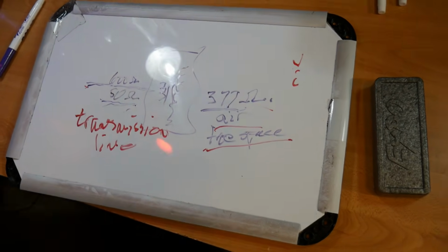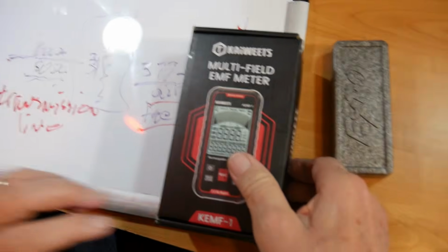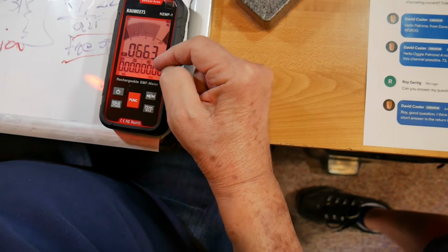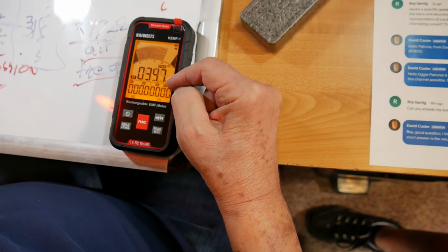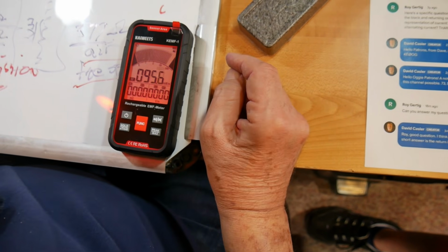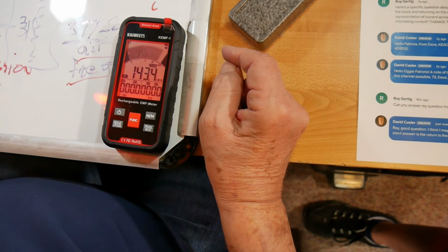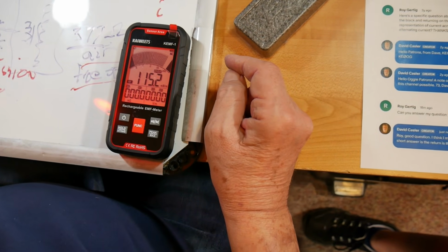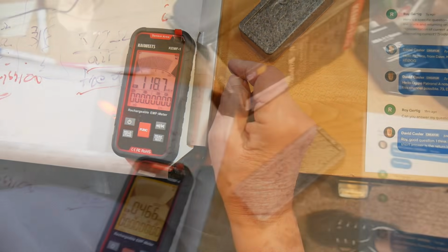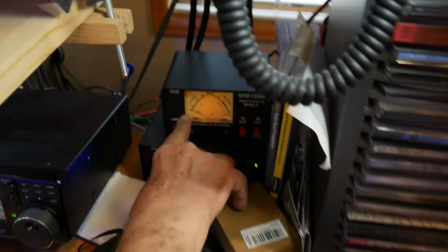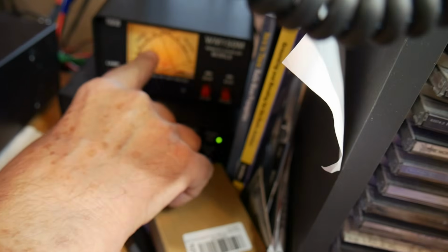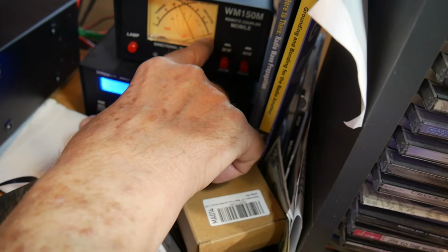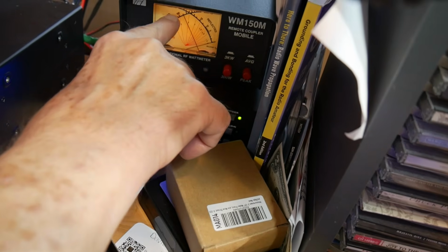And you see these field strength meters. This is a field strength meter right here. Now there is a RF, and this is milliwatts per meter squared, okay? Now if I were to turn this on, okay, it's in CW, so I'm going to push this. You don't see much here. We're transmitting, see? And again, we're interested in power, because that's the power going forward. Now you can see there's hardly any reflected power right there. Most of the power goes forward.